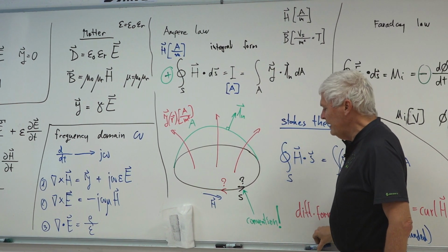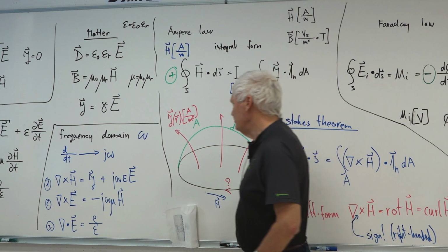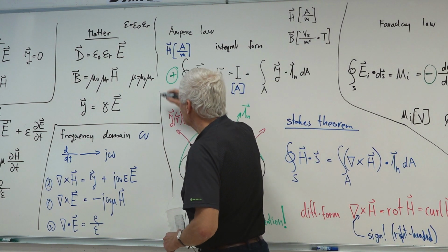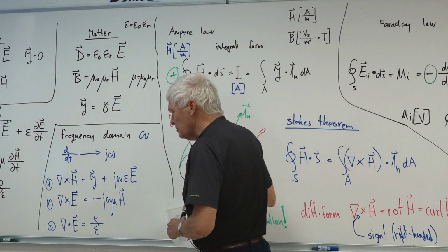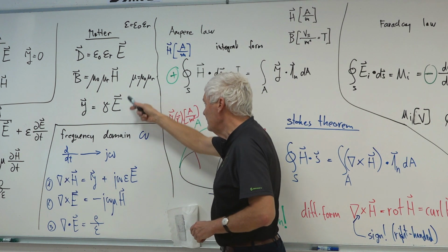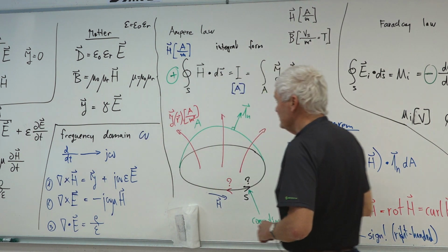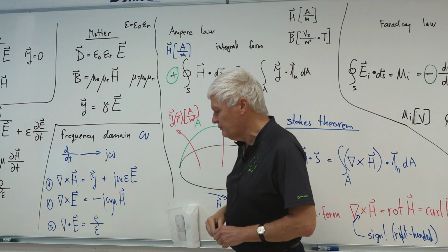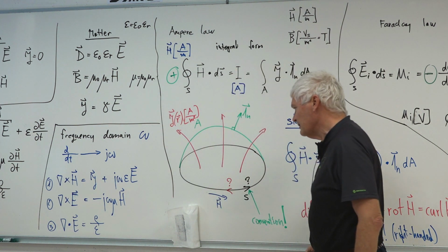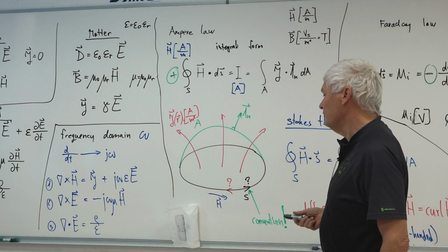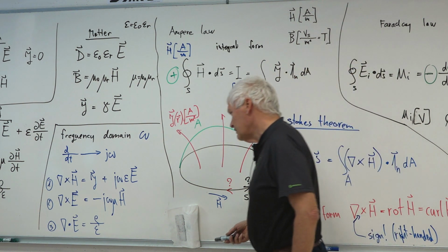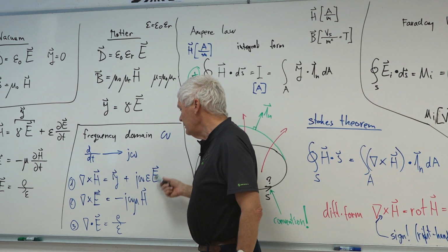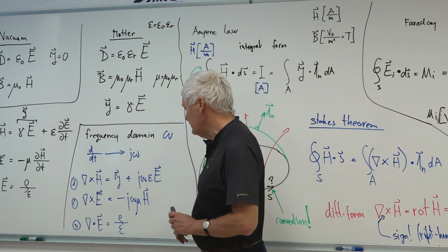Well, at high frequencies where we build antennas, matter is almost perfectly linear, so we don't see this nonlinearity, and we can use these simple equations. Of course, if we are building electrical machines for a power station operating at 50 Hertz, then we should take account of this nonlinearity, and equations are no longer linear. These equations for antennas are always linear.